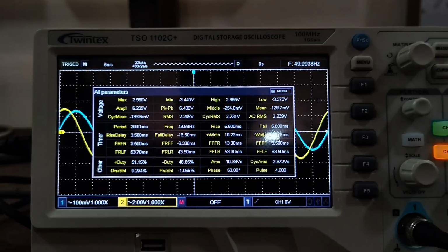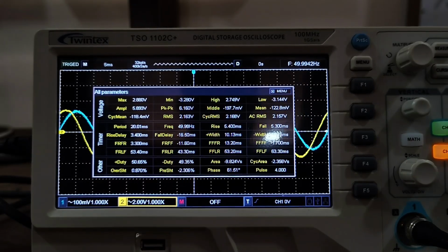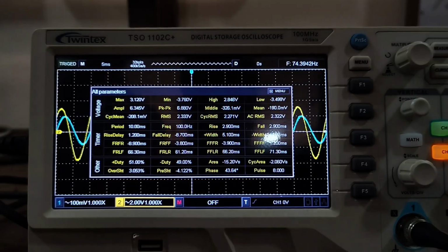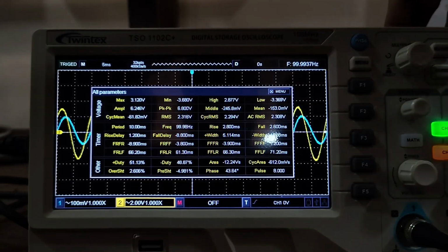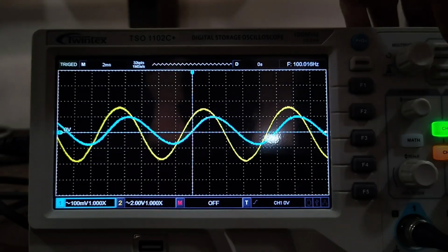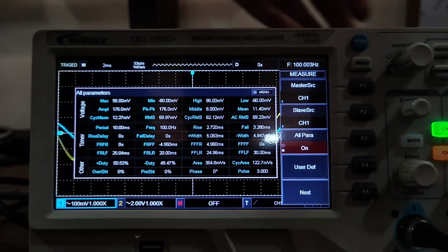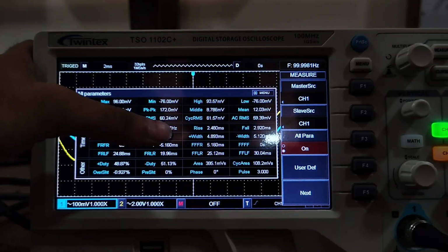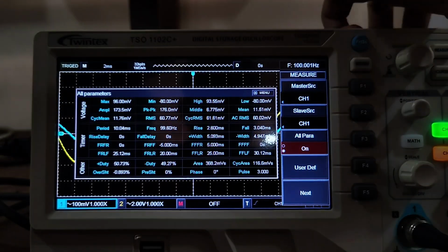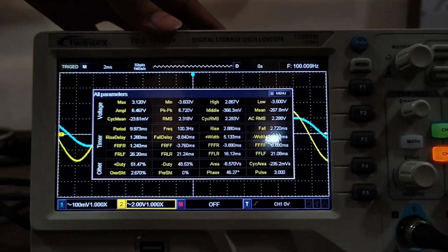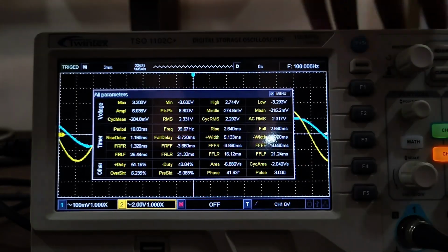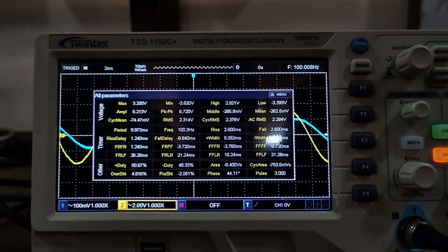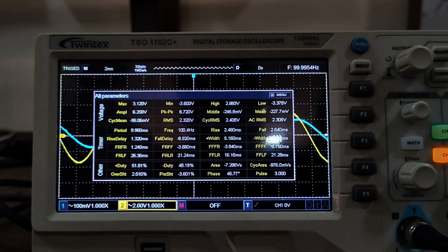So now we will take frequency at 100 Hz. So if we take 100 Hz frequency, now we will show the output in the oscilloscope here. So here channel 1 shows that peak to peak is 176 millivolt, and now we will show channel 2. So channel 2 shows 6.7 volt. So now we see that here the graph is sloping upward for the frequencies 10 to 100 Hz.